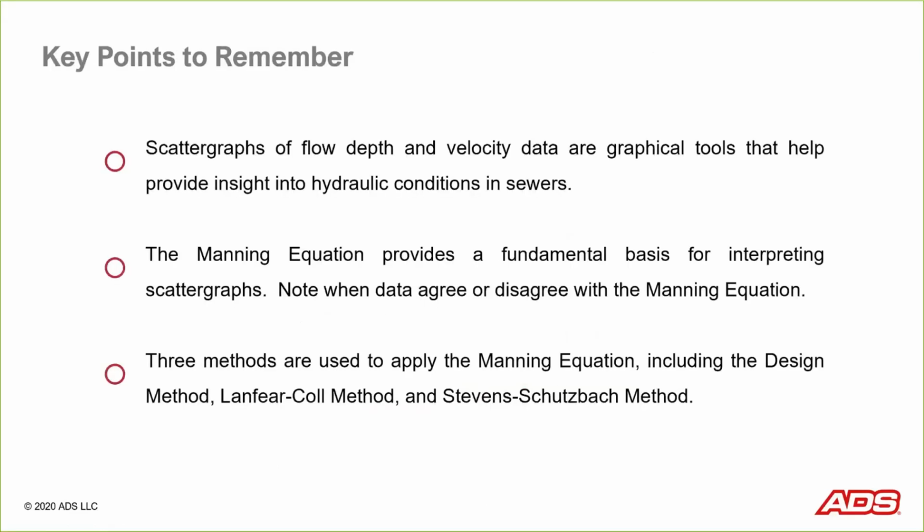So I want to wind this down a little bit. I want to talk about three key points that I want you to remember from this fundamentals presentation today. One is that scattergraphs of flow depth and velocity data are graphical tools that help provide insight into hydraulic conditions in sewers. So think about the hydrograph as telling us what comes down the pipe and when. Think about the scattergraph as telling us how that pipe handles that flow.